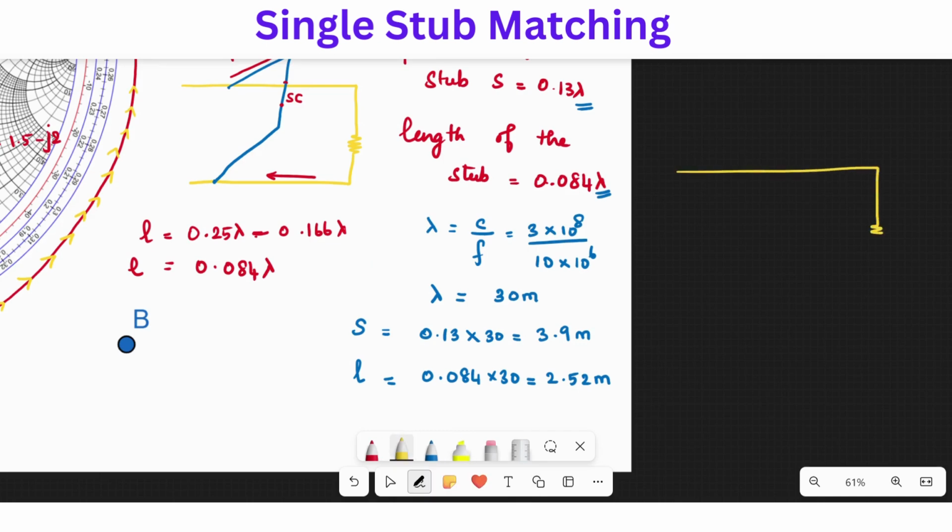We have a transmission line, and we have marked the load ZL bar. From ZL bar, we have observed YL bar, and at a particular distance we position a stub. The distance of the stub, denoted S, is 3.9 meters, and the length of the stub is going to be 2.52 meters.